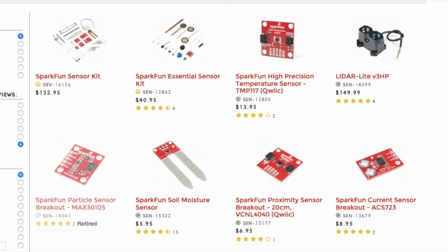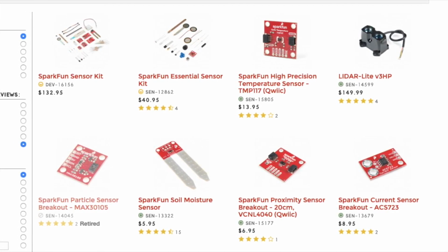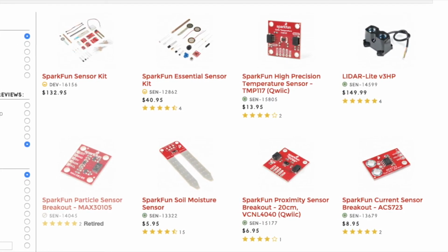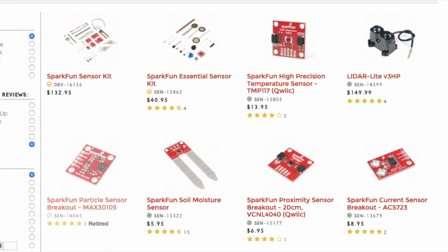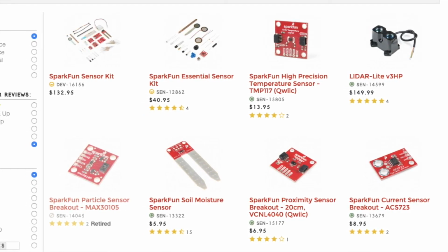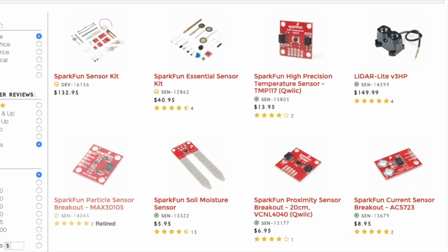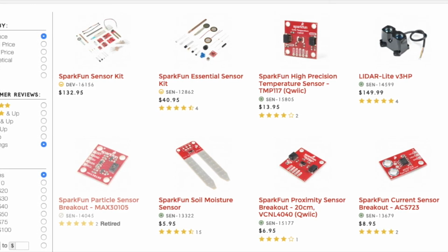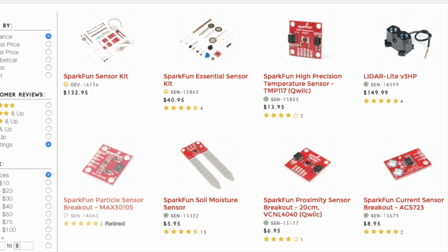You can control any number of input-output devices using the digital and analog pins on the Circuit Playground Express. You can even control sensors, which use some relatively advanced protocols, like serial and I2C. One thing to note when using external sensors is the logic level of the sensor. 3.3 volts and 5 volts are two very common control voltages that sensors are built to run on.